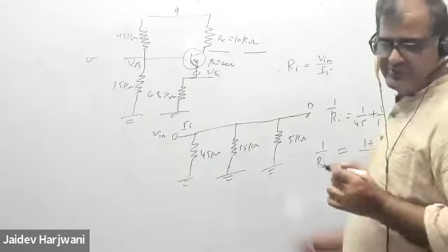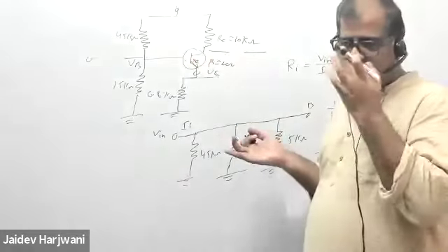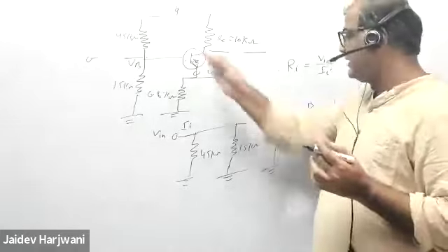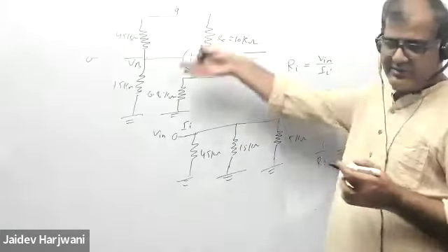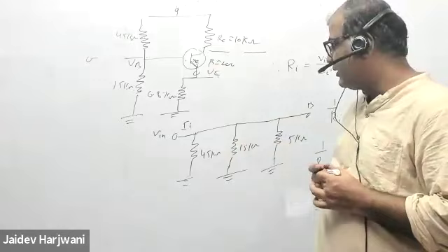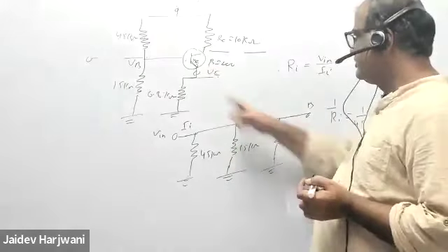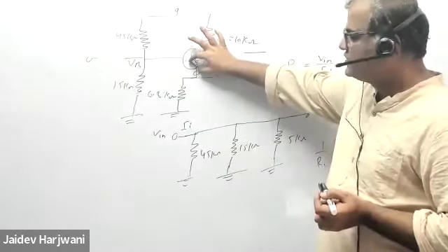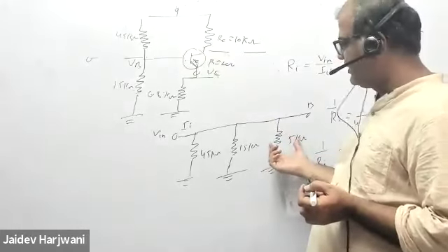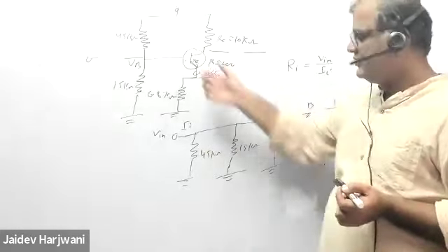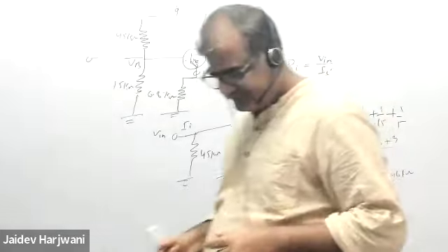Okay. अभी जिसने कर रखा है उसी समझ में आएगा, जिसने बिल्कुल नहीं कर रखा उसको क्या समझ में आएगा कि मैंने ये कैसे किया. ओके, so ये just in short I'm doing. Okay, so this junction will be replaced by a resistance of beta Re. So beta Re plus this one, they'll give you the input resistance.